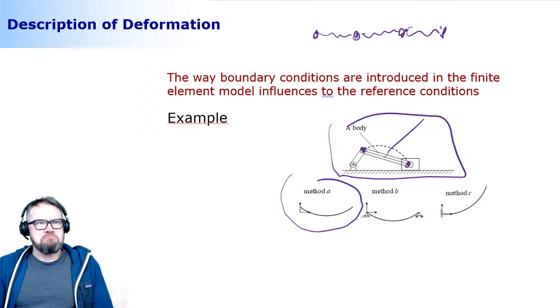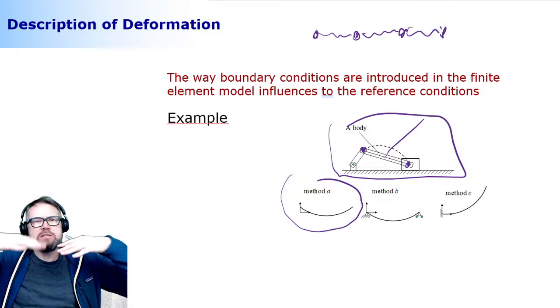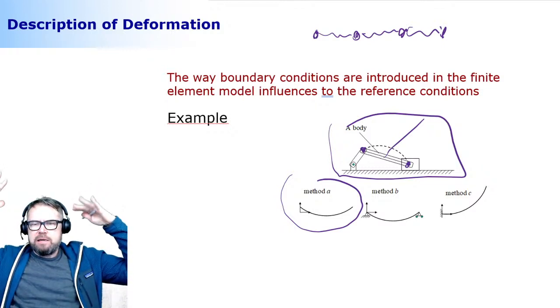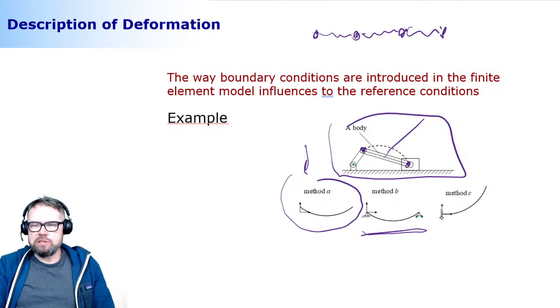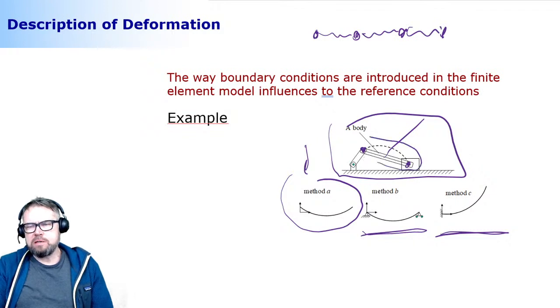Should I use no boundary condition whatsoever, meaning that the structure is kind of floating in space? And when it is floating in space, this is how the relation between the reference condition and the deformation mode looks. Or should I use a simply supported beam condition? Well, this is a clear example of the simply supported beam condition. Or should I use a fixed boundary condition, in a way that one end of the structure is connected to ground? Which is the correct way? Which represents the best situation in a real structure when I'm combining this into my multi-body model?